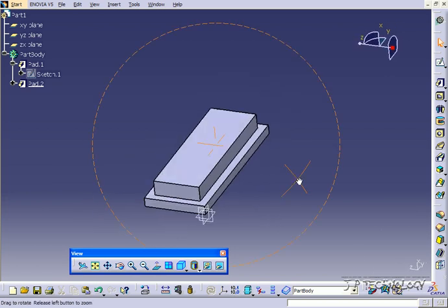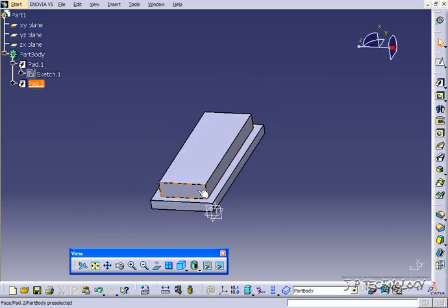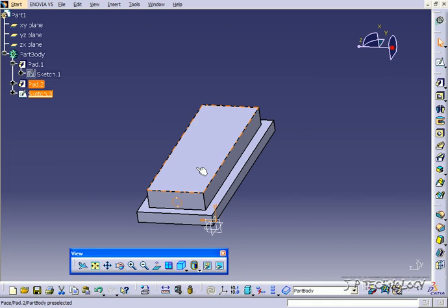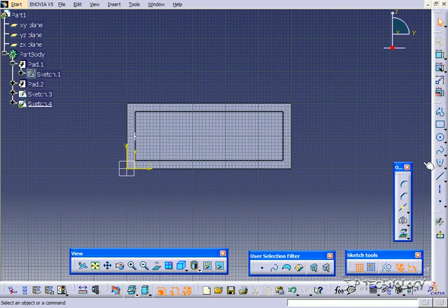This time let's create one that isn't a square. So let's do a circle like we did on the last one. Let's click this face, click sketch, and we'll click circle. Just draw a little circle in there, and we'll go back, click the top face here, click sketch, and as we're going to be able to cut through this, we can make a route for it to follow.